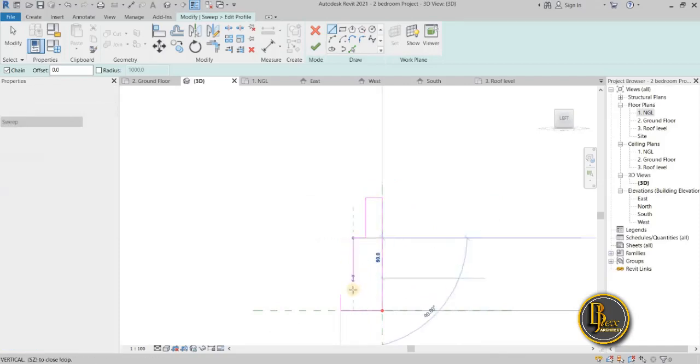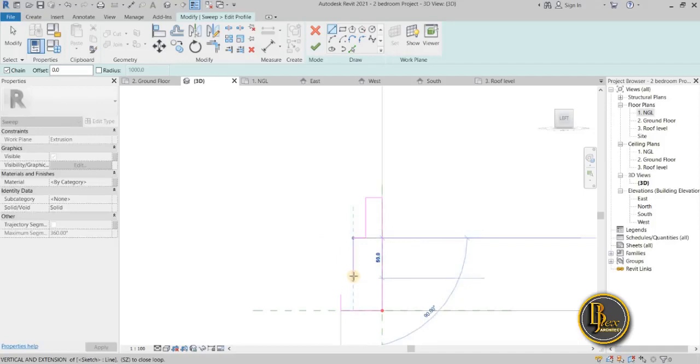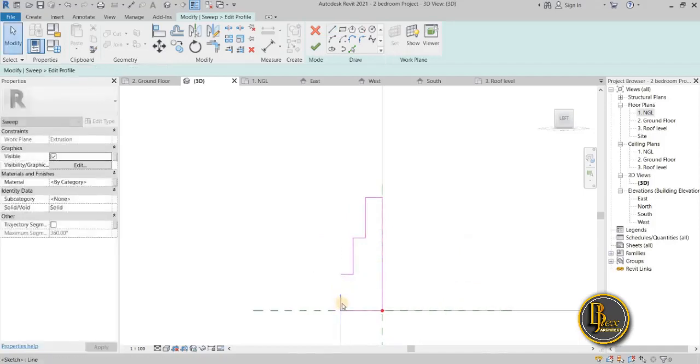I still hope you understand how to create sweep. Just the way you created floors, you use sweep in creating floors and creating stairs. It's the same thing we are doing here. We are using sweep to create columns and all that. So that's what you use sweep for. So let us use an arc tool to get this point. Delete this thing. Let's use an arc tool. Arc, yes. Then pick this so that we can get all those extra curves that you see